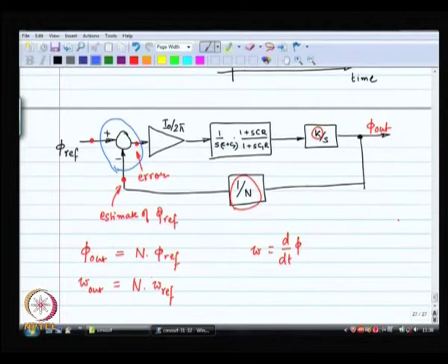I do not have a plus minus over there, I have got two flip flops, they are giving me a digital output and the time for which it is 1 or minus 1 gives me the estimate of the phase error, right. So, there is an averaging that I am implicitly doing over there in my analysis, right. So, that is where the bandwidth limitation of my control system came from.